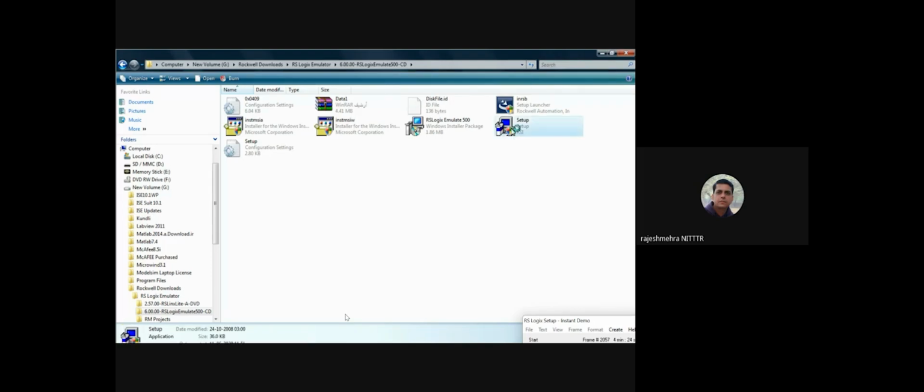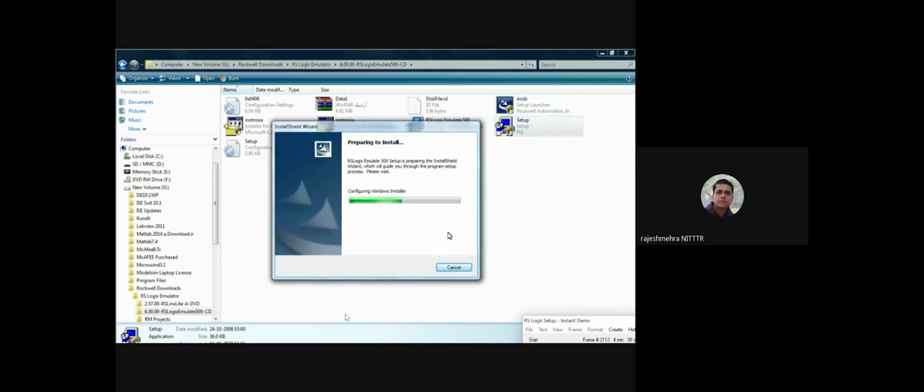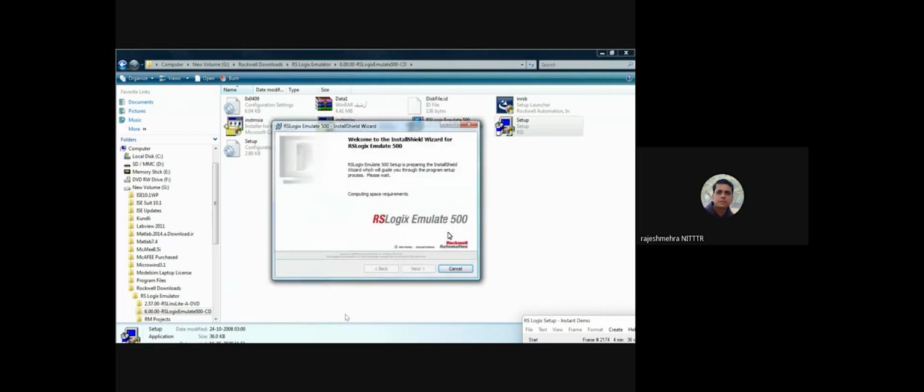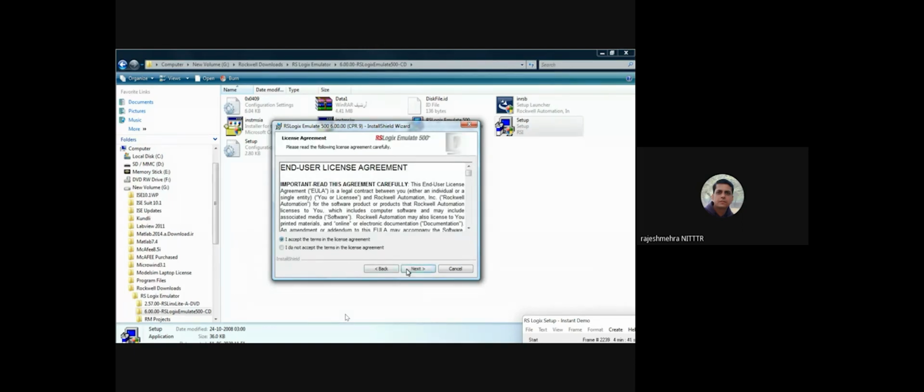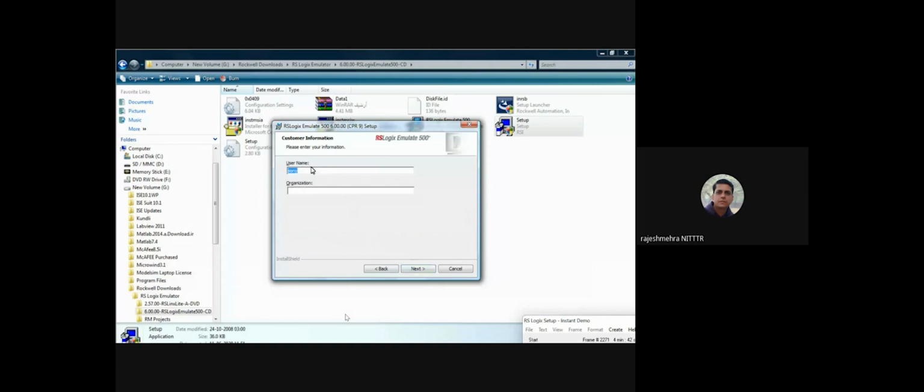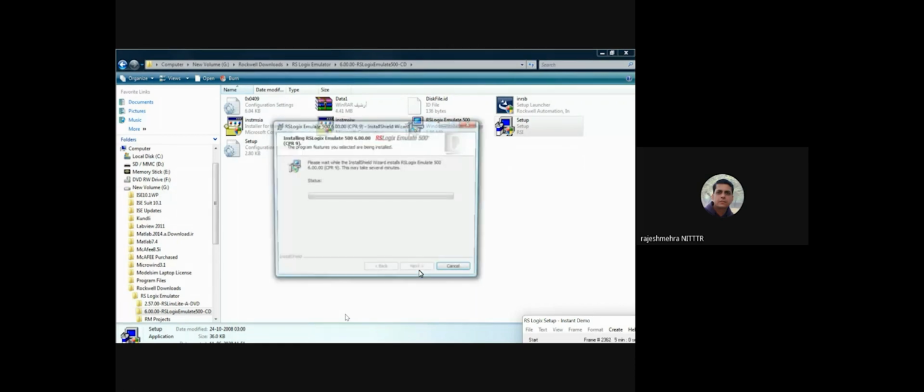Now we are going for the second installation, the second software, and this software is RS Links that contains RS Logix Emulate. Again, you can give your name. Again, we can select complete and install.